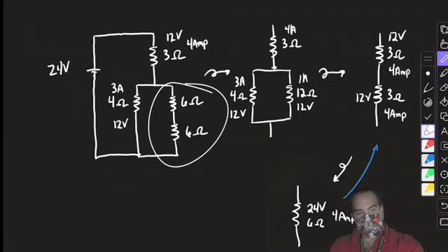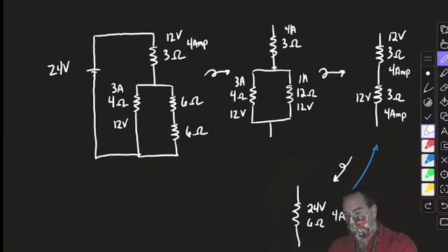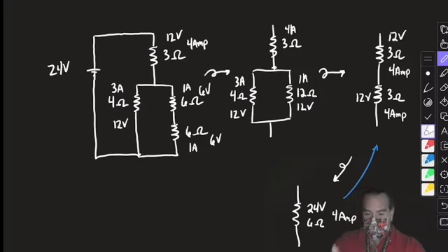leaving just these two. And I'm going to take the current and apply it to each of them. Since they're in series, they must have the same current. And now Ohm's law, once again, 6 volts, 6 volts. And it looks to me like we have successfully solved our circuit.